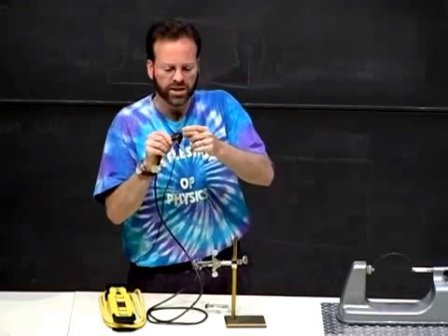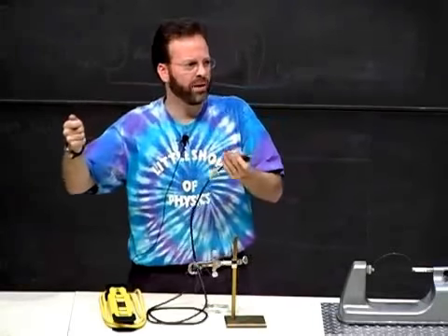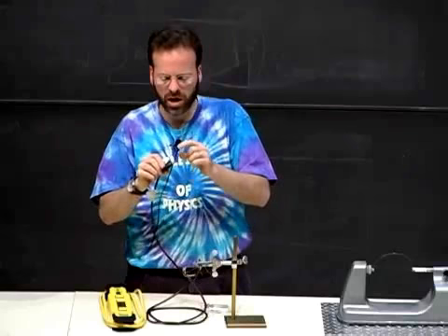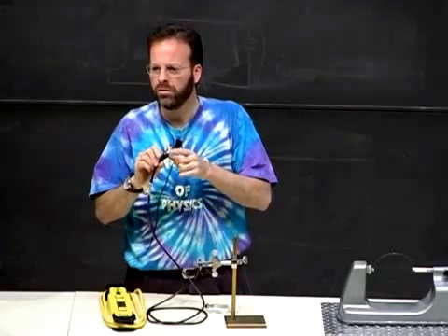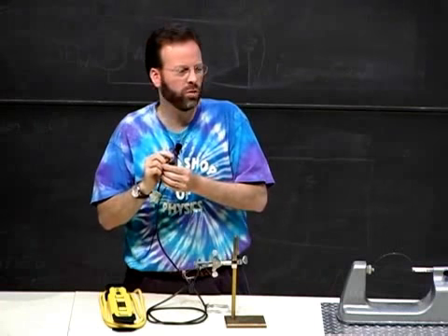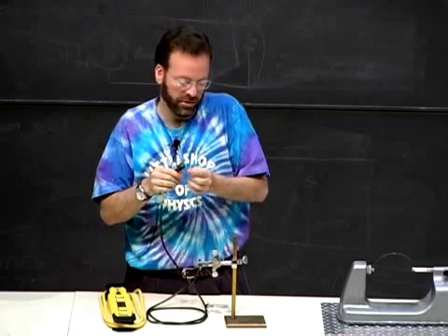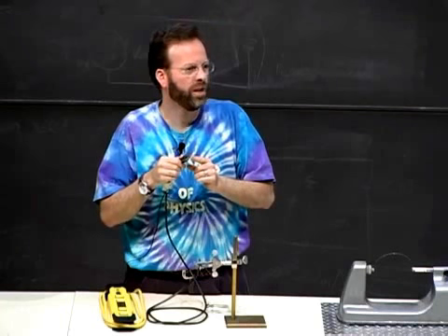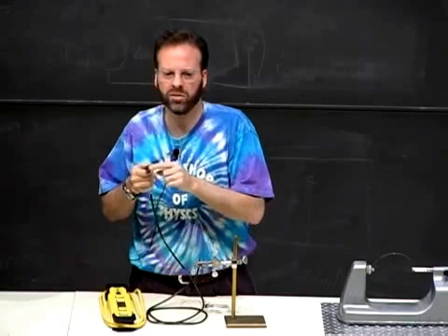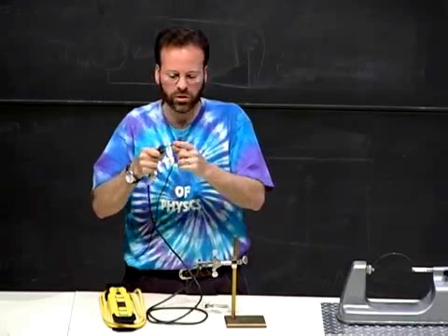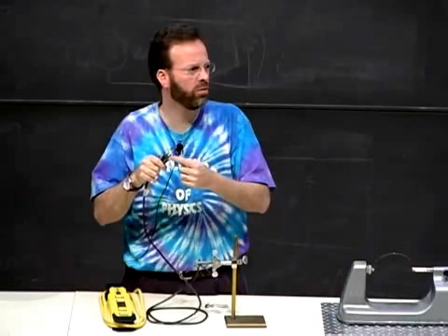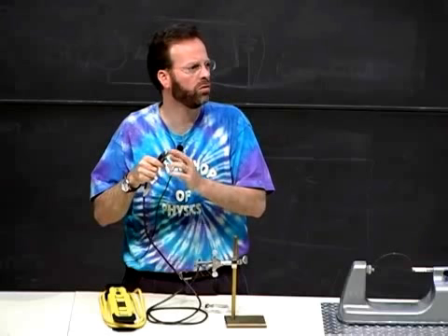These two are essentially like the two sides of your battery, positive and negative. They call them hot and neutral. You can have a high voltage on one side and a different voltage on the other, a low. The low is not always zero, but you'd like it to be. And in most circuits, the neutral is the low and connected to ground. So they're both at 0 volts.